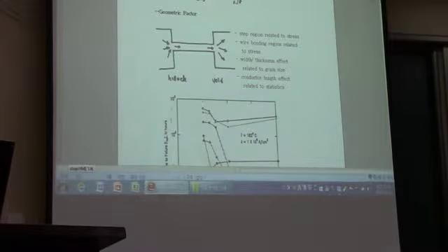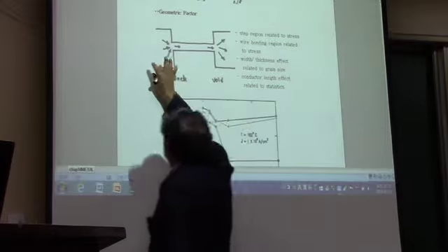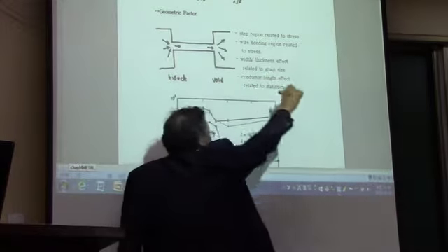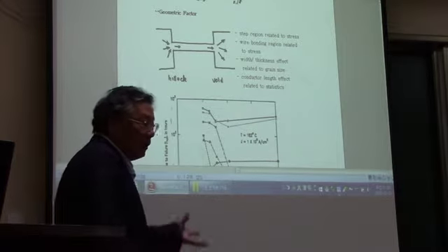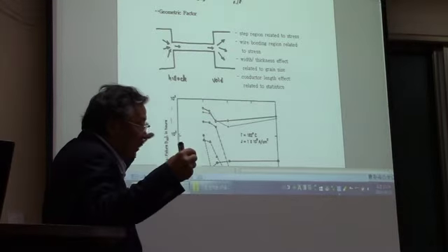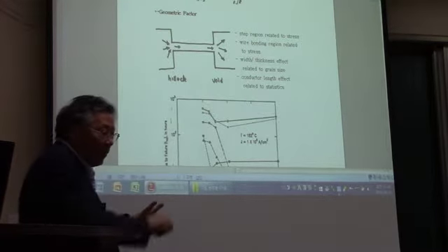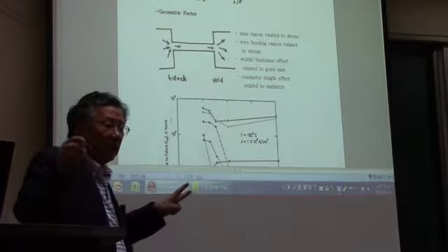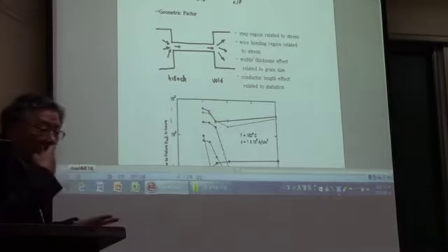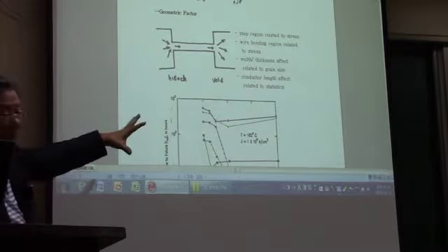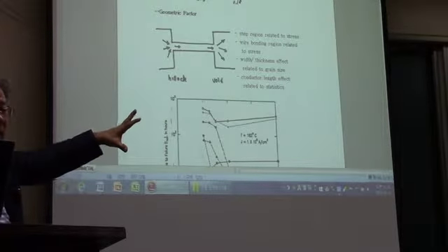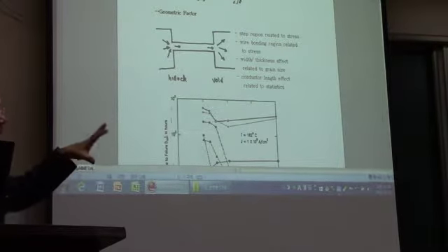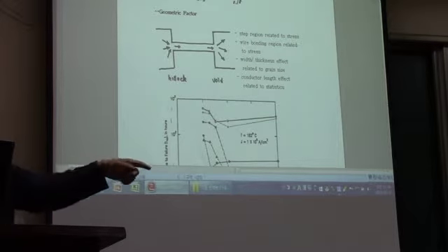And you just discussed the grain boundary effect, right? Now the geometry effect. When you have a pad with a large size, and then you have metal lines. Metallization consists of two things. One is the metal lines connecting each of the transistors, and the other is the formation of the pad, which is going to work as an input and output